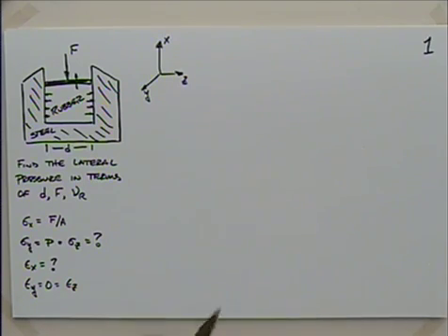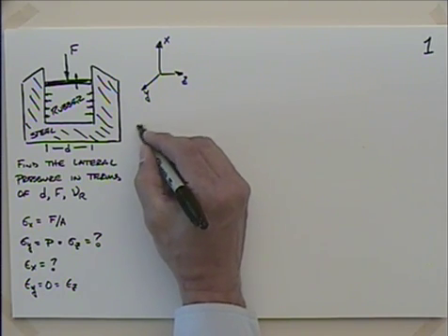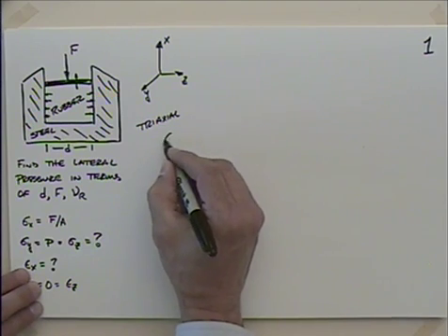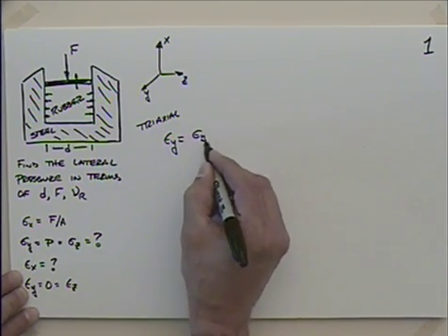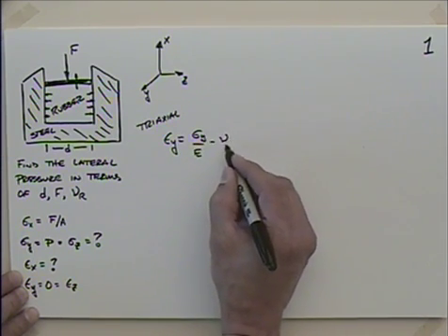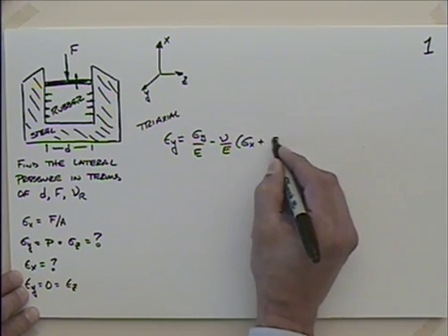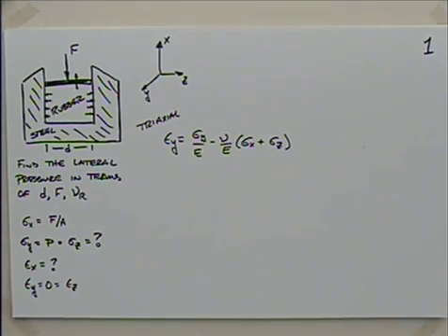So with that at hand, I can go and look at Hooke's law, and I'm going to use the triaxial, the full 3D equation, where we can say that epsilon y is equal to sigma y divided by Young's modulus minus Poisson's ratio over Young's modulus times sigma x plus sigma z, I think we had. When we went through those expressions, you can go back in your notes and look those up, but I think that's correct. So let's put what we know into this thing.